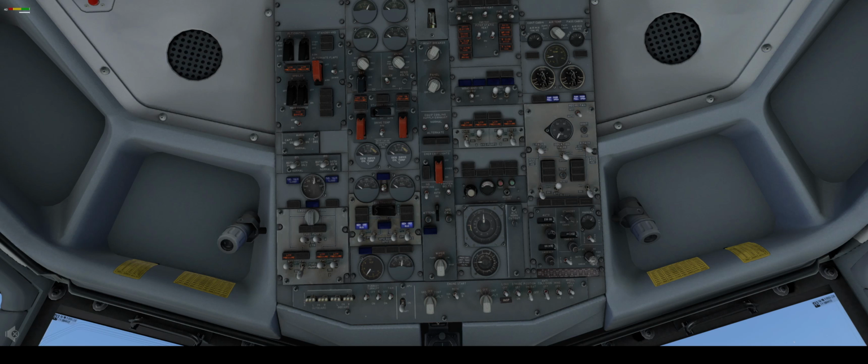There are as well fuel limitations and hydraulic limitations, center tank fuel limitations, and so on. Basically we go through all of it, and there is one thing I would like to point out. As the APU is not so powerful, we make procedures in order to get fresh air into the cabin this way.